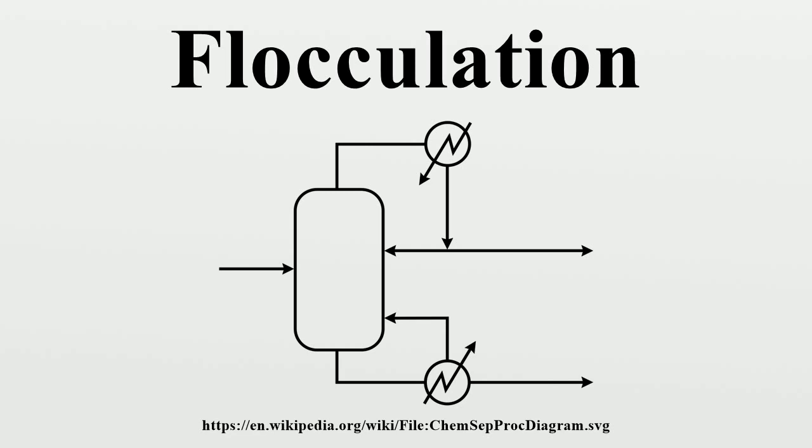Cheese industry. Flocculation is widely employed to measure the progress of curd formation in the initial stages of cheese making to determine how long the curds must set. The reaction involving the rennet micelles is modeled by Smoluchowski kinetics. Flocculation is also used during cheese wastewater treatment. Three different coagulants are mainly used: iron(II) sulfate, aluminum sulfate, and iron(III) chloride.